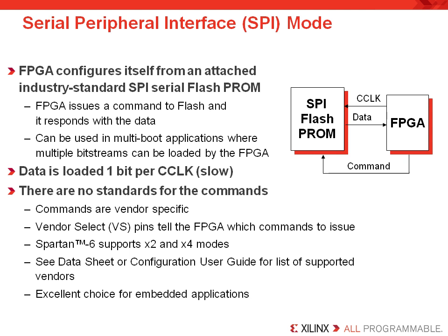You should also be aware that if your daisy chain contains multiple FPGAs in the configuration scheme, your flash PROM will need to be big enough to contain all the bitstreams in the chain. Likewise, this is a popular configuration for designers that want to load a single FPGA with different bitstreams at different times while their application is still running. This reconfiguration is referred to as multi-boot applications and should be planned sufficiently so you can choose a SPI flash PROM that is large enough to accommodate all the additional necessary bitstreams.